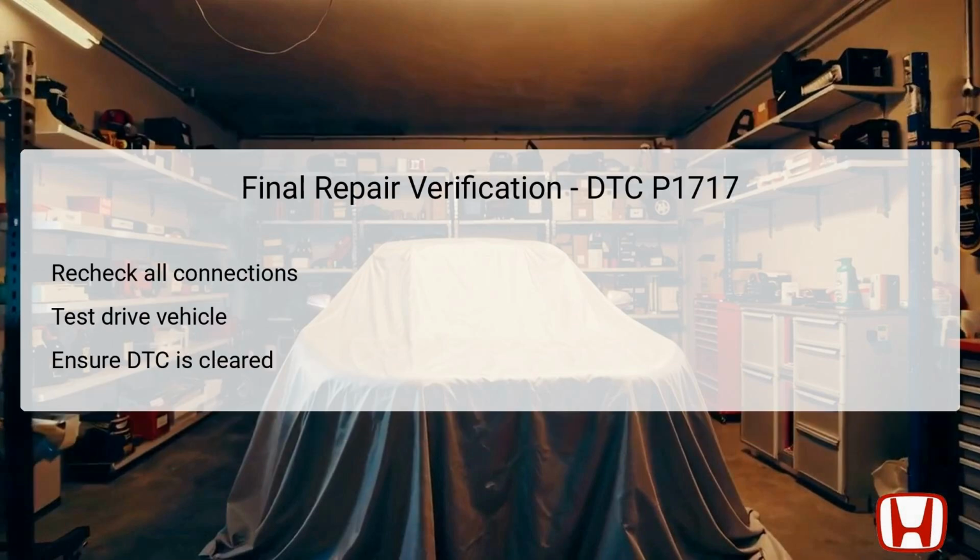After completing the prescribed troubleshooting steps and taking the necessary corrective actions, it is essential to perform a final repair verification. Start by carefully rechecking all connections made during the maintenance procedures to make sure everything is secure and properly aligned. This step ensures that potential issues caused by loose or poor connections are eliminated. Following this, conduct a test drive to allow the vehicle to go through various gear changes, particularly into reverse, to confirm that the problem has been resolved.